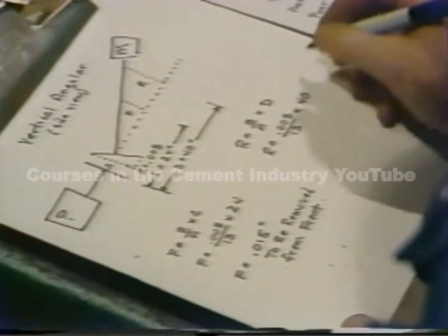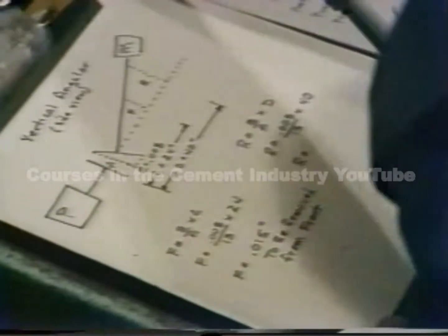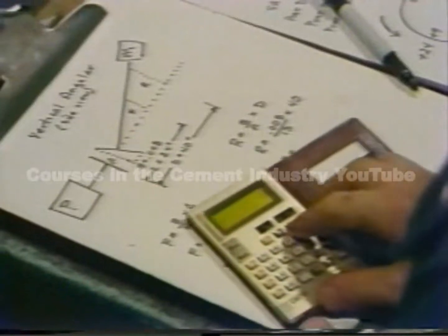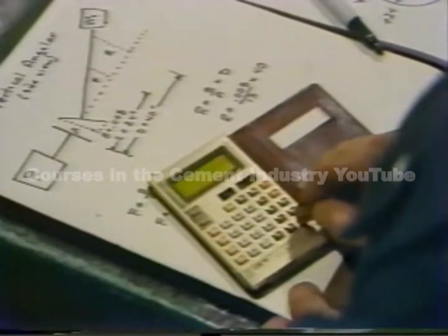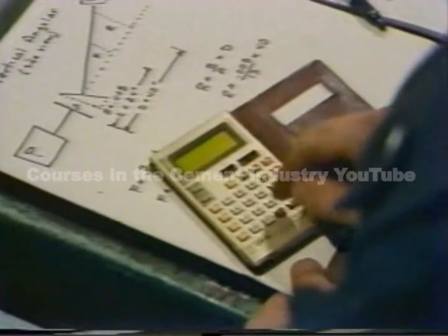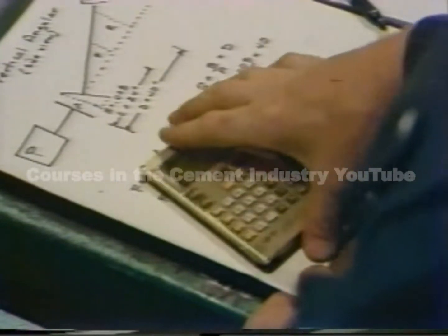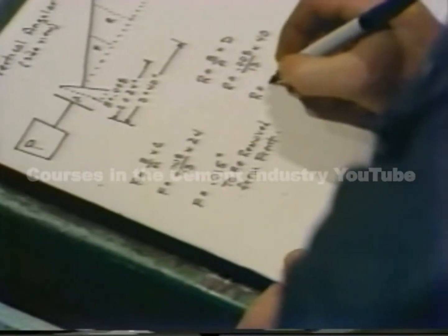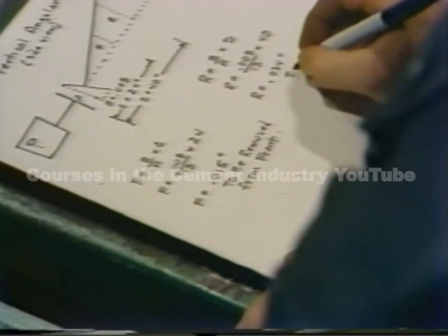So essentially it's the same equation, except that we use the distance to the rear feet, which was 40 inches in this instance. The calculation in this case comes out to 24 thousandths of an inch. So 24 thousandths must be removed from the rear feet.